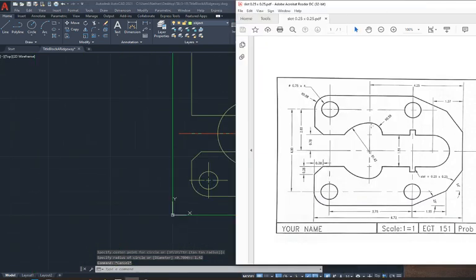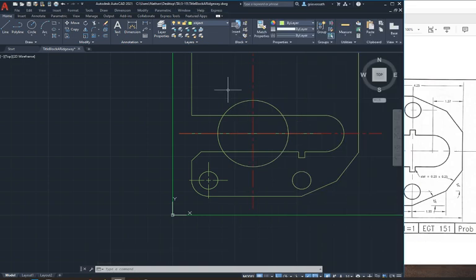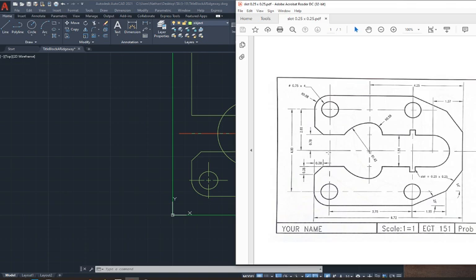And there we go. There's our initial circle. So next, let's draw our smaller circles. Now, you might be thinking to yourself, hey, these smaller circles are aligned with this line. You can see it right there, you know? But this is where the layering and the center lines and whatnot are important, right? Since there is no center line drawn across here, that means that we aren't told for sure that this is an alignment here. There's no hidden line drawn across it or anything else.